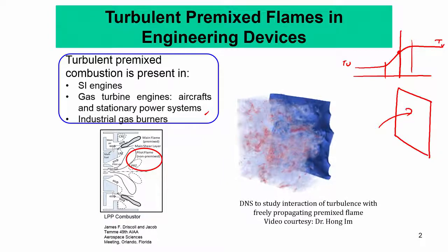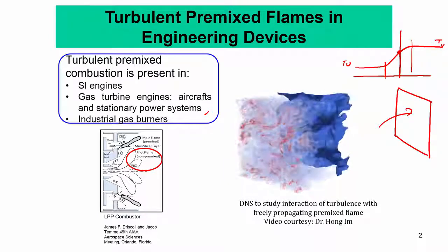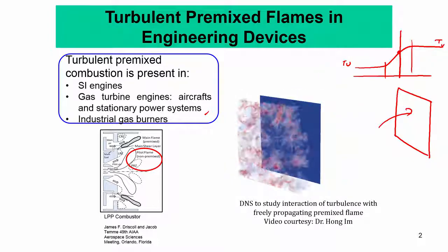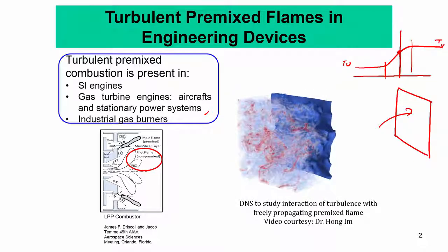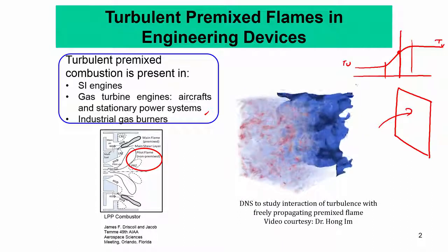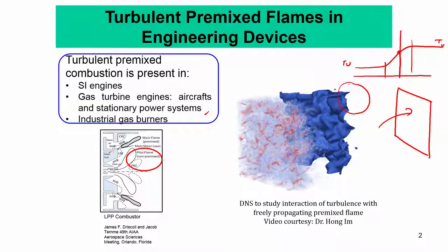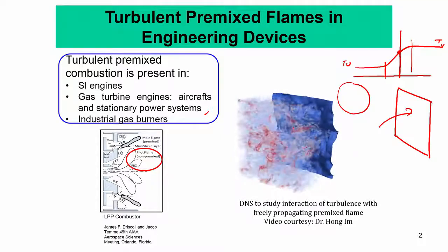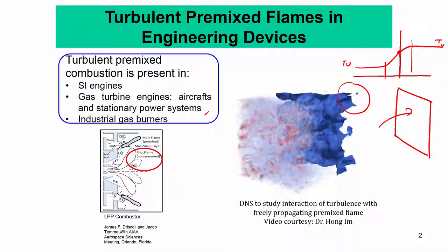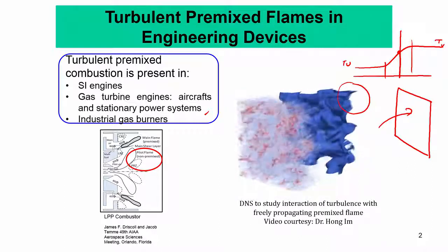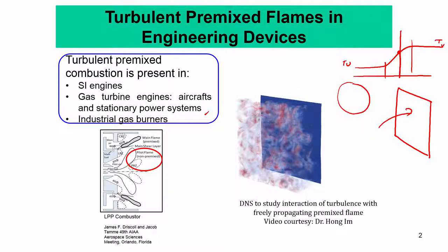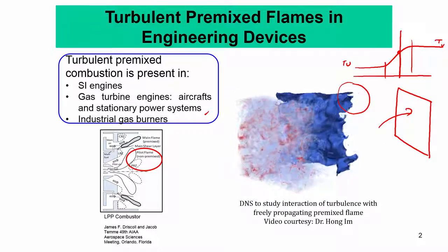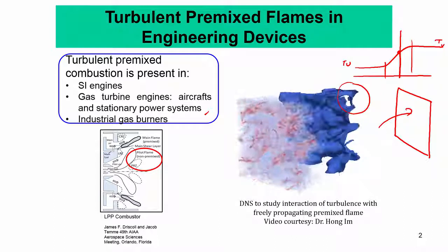Okay, and these length and time scales are controlled by both turbulence as well as the intrinsic flame properties. Okay, and then after it folds and wrinkles the premix flame at a multitude of length and time scales, you see that this surface essentially annihilates in the trailing regions of the flame. So, this turbulence essentially stretches, folds and wrinkles the surface at different length and time scales, and then this surface is actually destroyed. Okay, this isosurface of temperature is actually destroyed. So, that means there is a continuous generation of surface also.